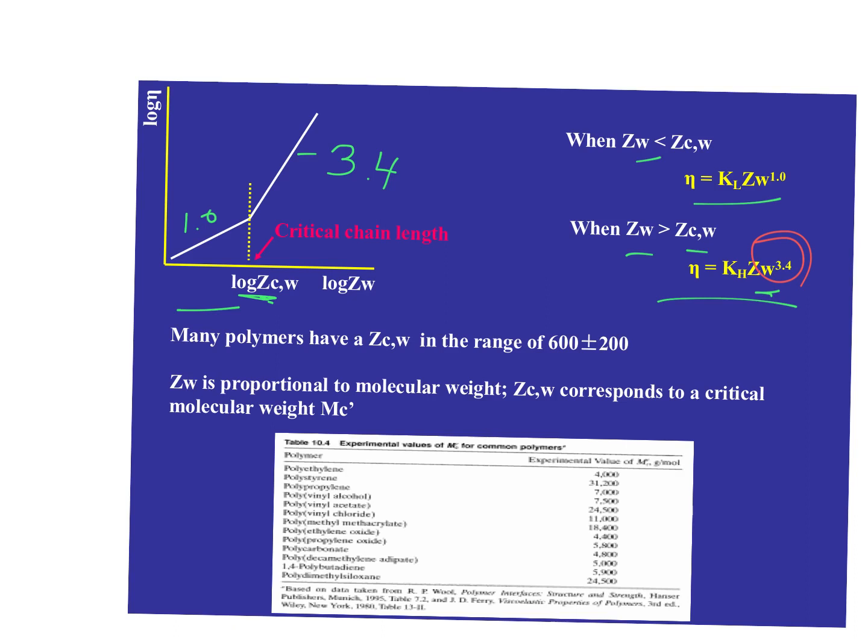Right? The viscosity just jacks way up because of all those entanglements associated with those higher molecular weights. All right, so there are limits here that get us beyond this point a little bit, but then after that, you forget about it. You're not going to be able to mold that using injection molding. You have to use some other process. Does that make sense to everyone?